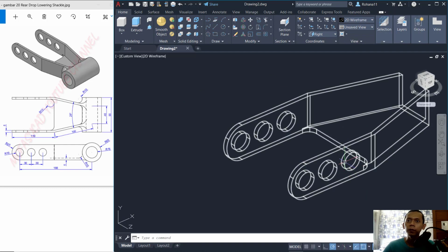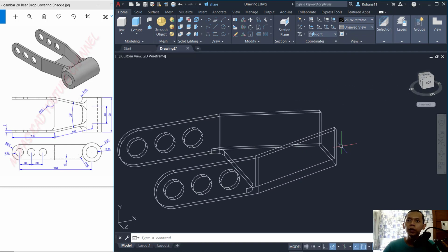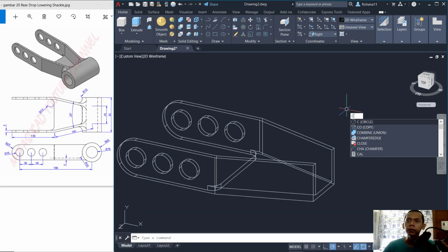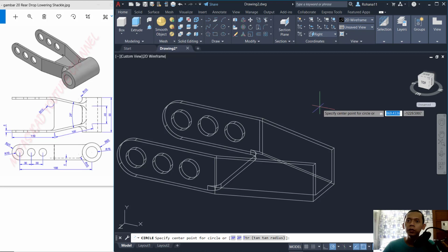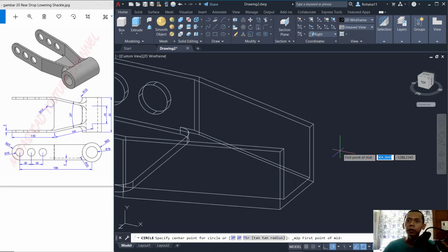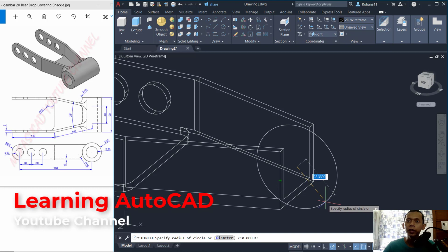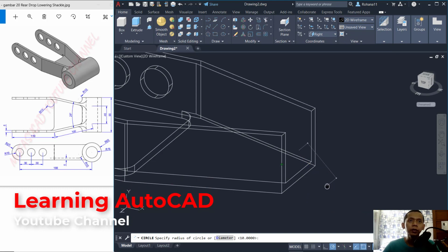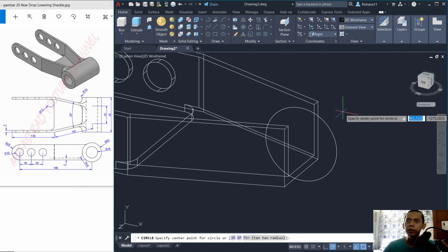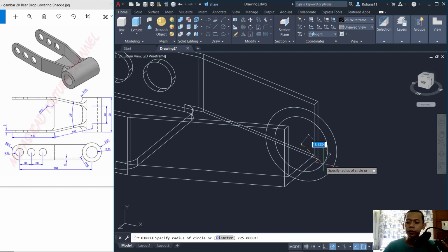quite tall in it. Now in the front here we can create a circle again. I will use the mid between 2 points for a base point. You can click from this point, middle point, and also in here, middle point, so it will be correct in the center point. We can set a radius of 25. The next we create a circle again from a center point. We can set a radius of 15.